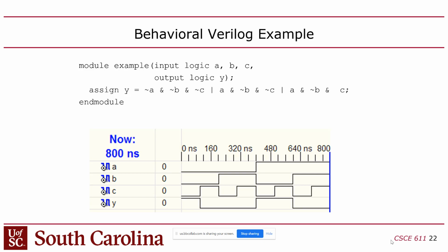You'll have your ALU op code, and you'll have your reg write signal. So you'll see, oh, the reg write goes high there. I must be writing a register, whatever that instruction is. So you can put your cursor there and see what's going on, right? Likewise, the first CPU we implement will be comprised entirely of R-type instructions, which always write the register, right? So in that case, you'll look at this and you better see a flat line for the reg write.